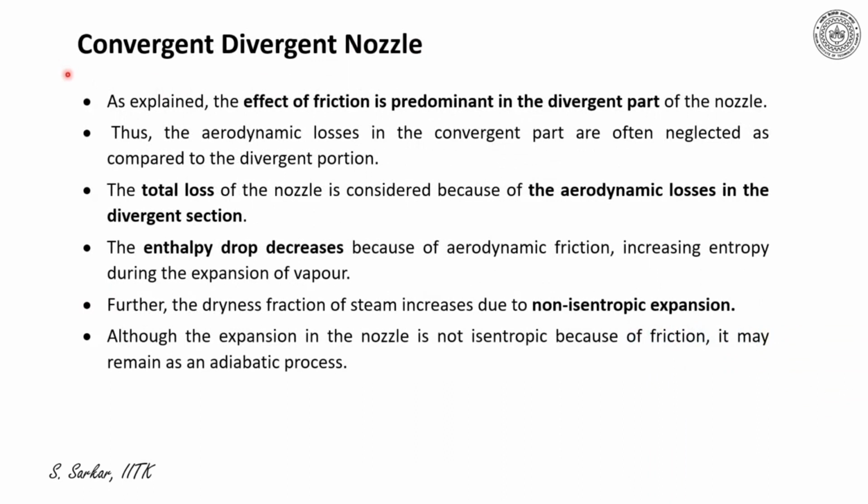Now we are considering the non-isentropic expansion of gas or vapor through the nozzle. As explained earlier, the effect of friction is predominant in the divergent part of the nozzle. Thus, the aerodynamic loss in the convergent part of the nozzle is often neglected as compared to the divergent section.